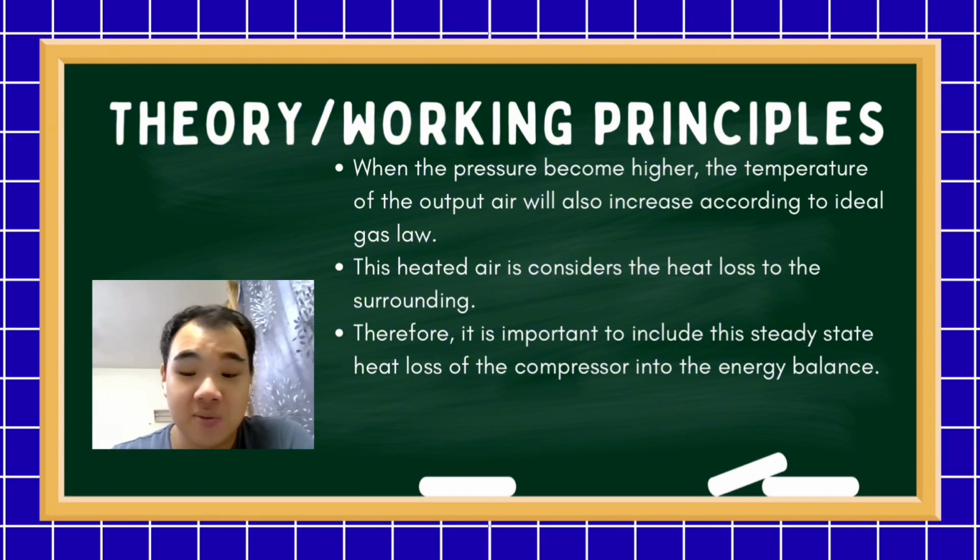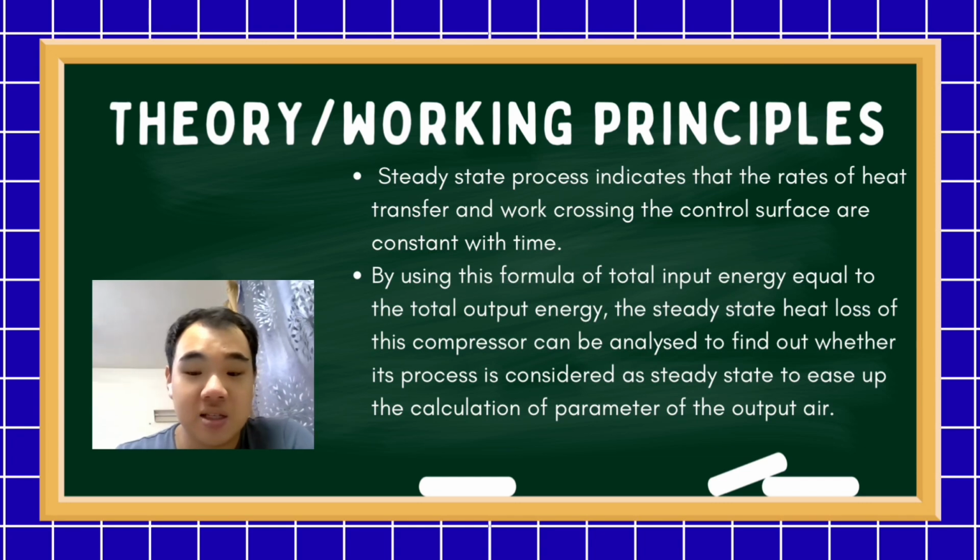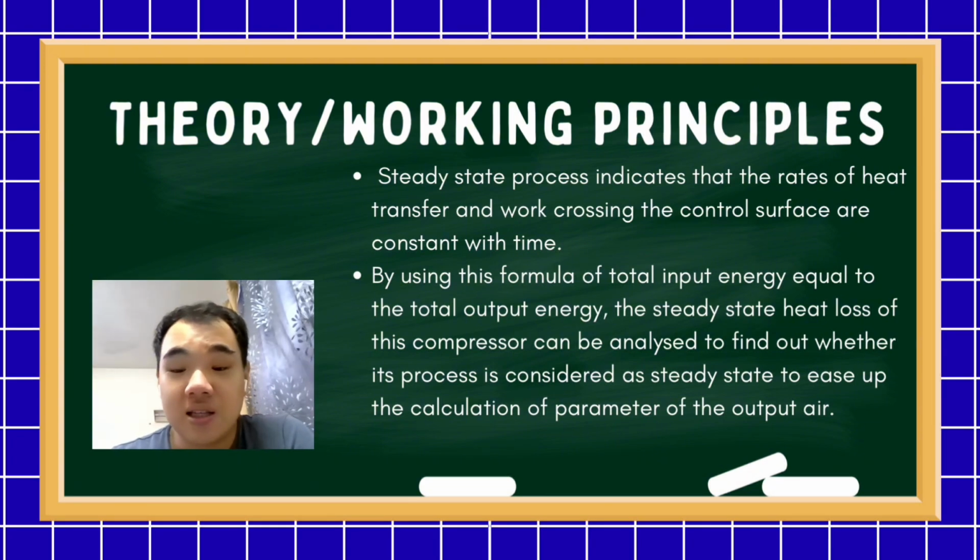So therefore, it is important to include this steady state heat loss of the compressor in the energy balance. For the steady state process, the rate of heat transfer and the work crossing the control surface area are constant with time. So by using this formula, total input energy equals total output energy, the steady state heat loss of this compressor can be analyzed to find out whether its process is considered steady state, to ease the calculation of the parameters of the output air.